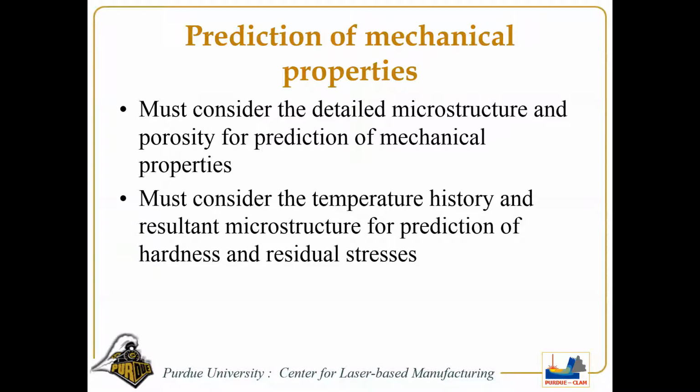So a lot of people think of the advantages of additive manufacturing processes. They get excited about that one, but they don't understand the difficulties and problems it actually contains. One of the problems that you will encounter is that the microstructure you produce is heterogeneous, not homogeneous, because locally the material is heated and cooled, and depending on how the laser beam is scanning the surface, you'll have different heating and cooling curves everywhere. Therefore, there is no way you get uniform microstructure. So you have to understand how these things are affecting the resultant mechanical properties. Some are good, some are bad.